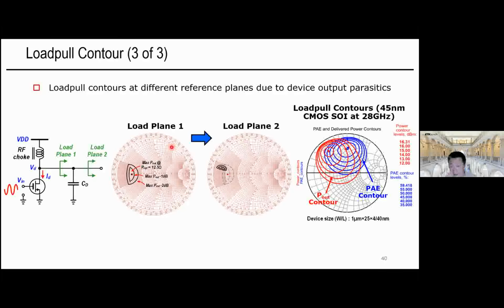Oh, that's a very good question, and I'm sure you have good experience on device level characterization. This really depends on the application, right? In many cases, when we start a design, we have to start from somewhere, and we often use the single tone as the excitation source so that we can find the optimum gamma L. But eventually, in many application design practices, later on you want to polish the PA. Often you may even want to use modulated tones to do that. And then going back to your question regarding the level of the input signal we should use to find the gamma L.